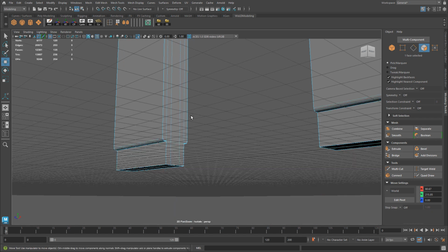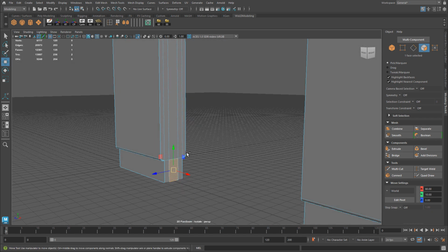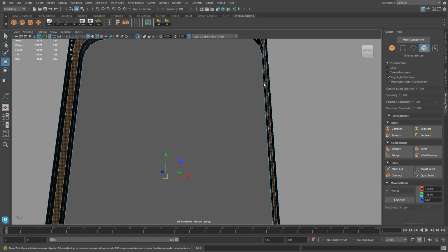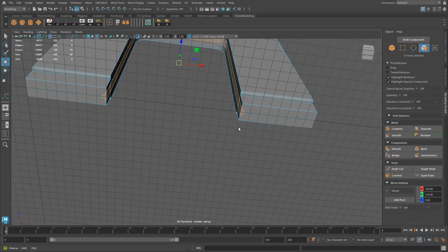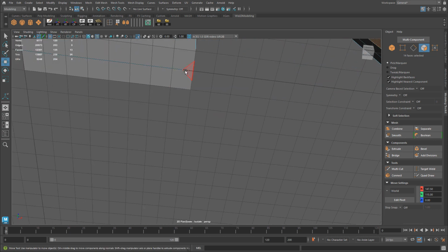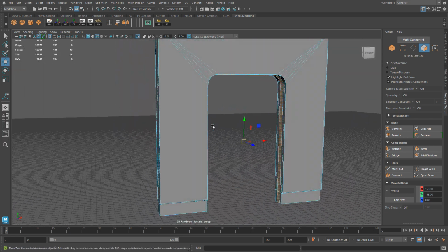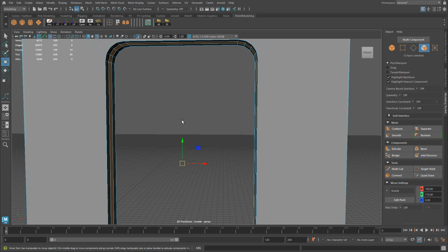And then I'm going to select all these faces that I want to extrude. I'm going to select the face on the bottom, then hold Shift and double click on the face next to it. It should only select the faces on the inside. Let me double check on the bottom. Oh, it has a bit of a triangle. So let's hold Control and deselect these two. So the only faces I have selected are on the inside. And now let's extrude them. Control E and add thickness of, let's do 5 for now.